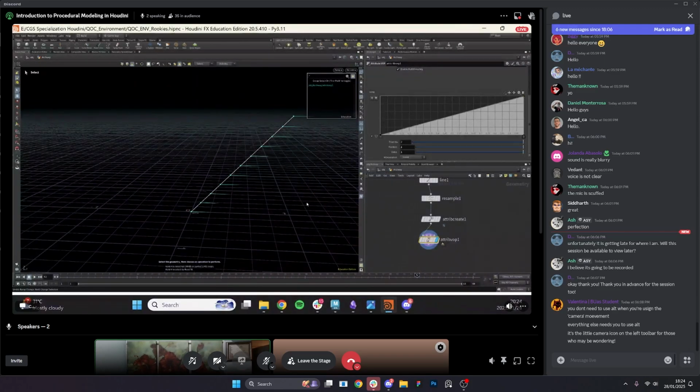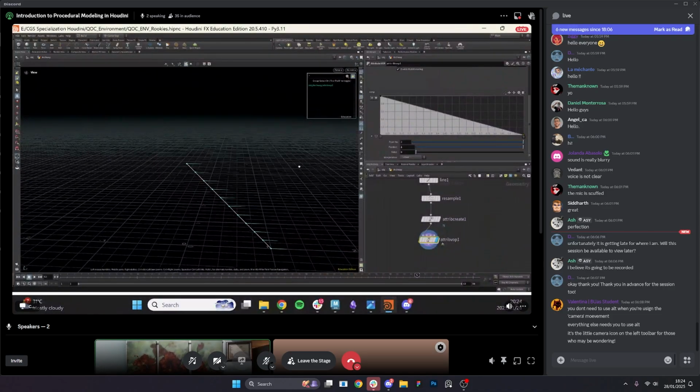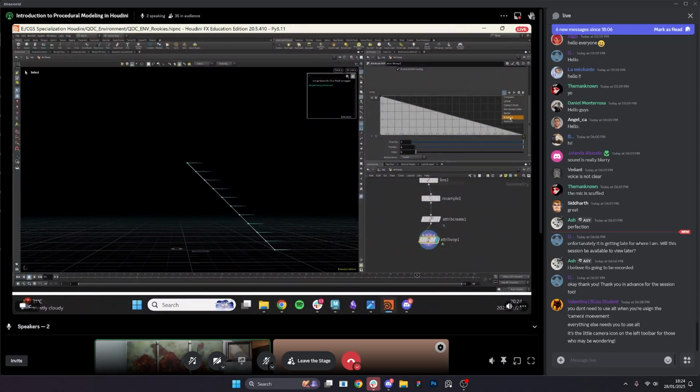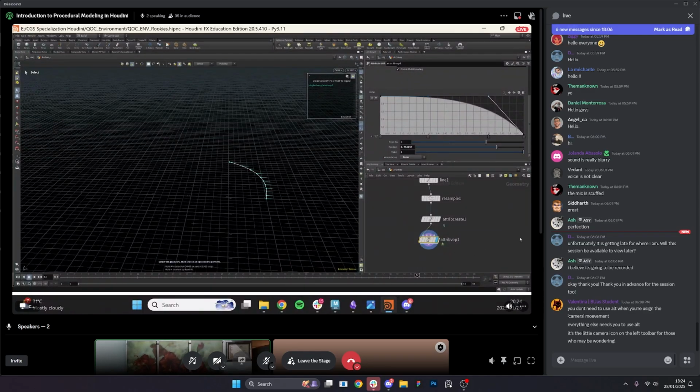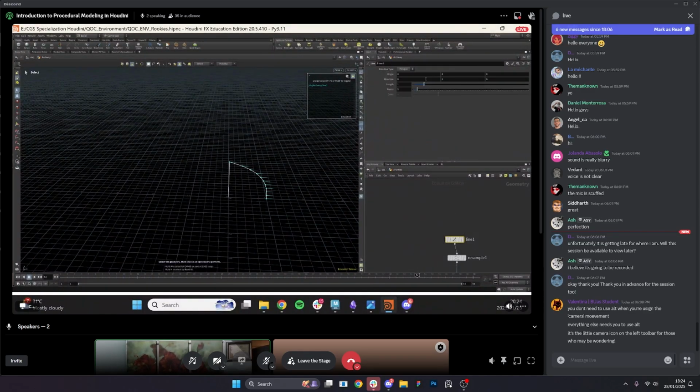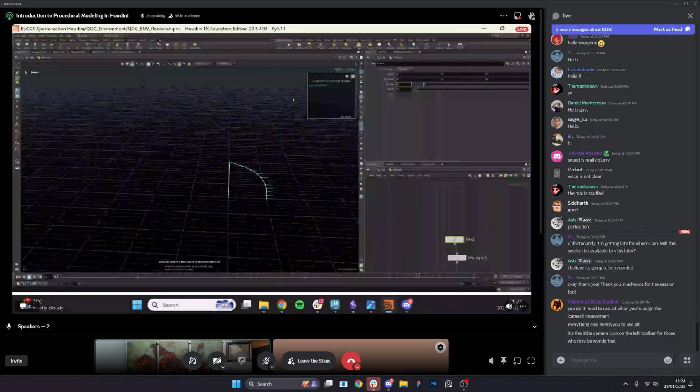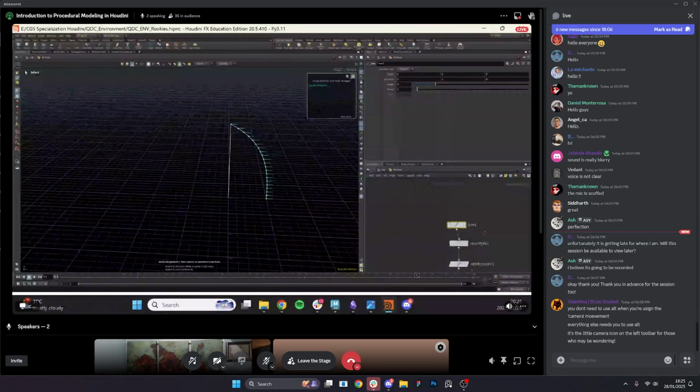So now we've got our system to build our curve. For this case, I'm going to flip it around and we're going to change it to Bezier because that gives a nicer curve, and change the shape. I'm noticing we've got a very flat arch here, so I'm going to go back up to the line and we're going to adjust the length to maybe 2.